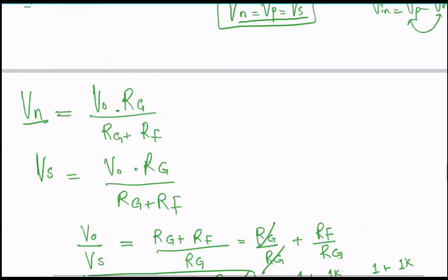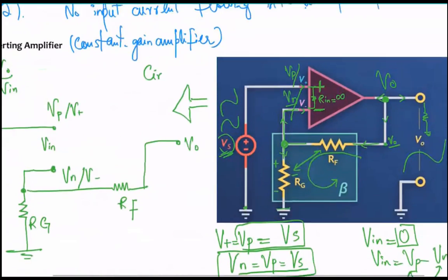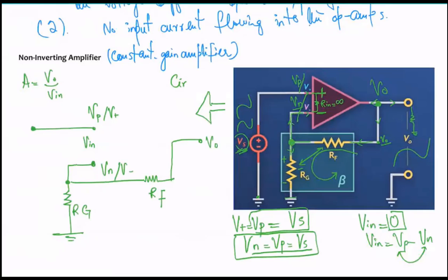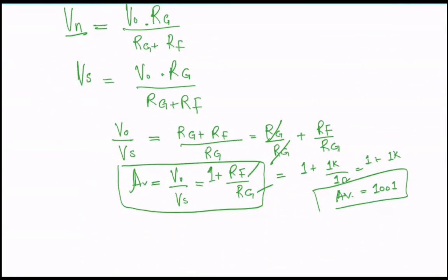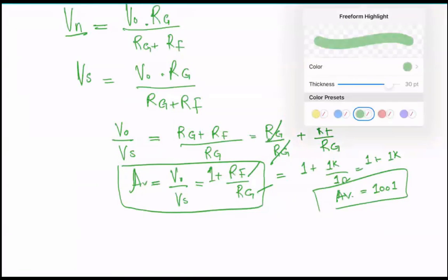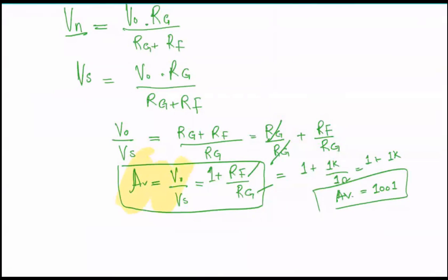So this is your non-inverting amplifier. The one we did on Tuesday was an inverting amplifier. Notice it has no negative sign in its expression, so you don't get a 180-degree phase shift. Both are widely used in AC circuits, but they just have two different equations to calculate the gain.